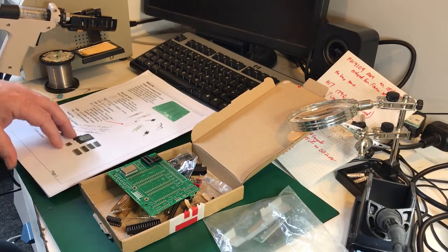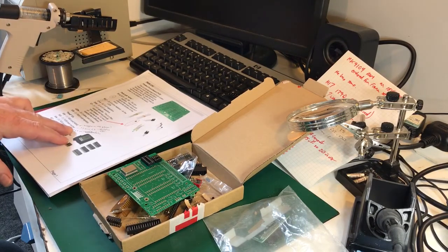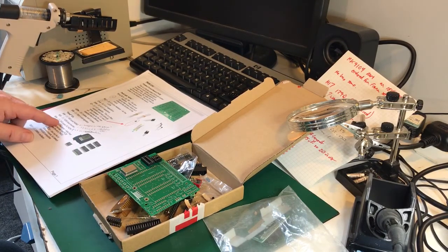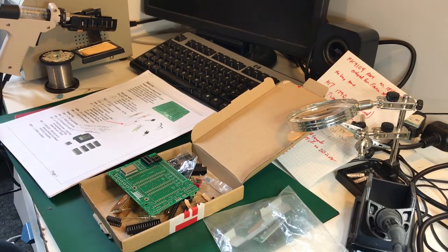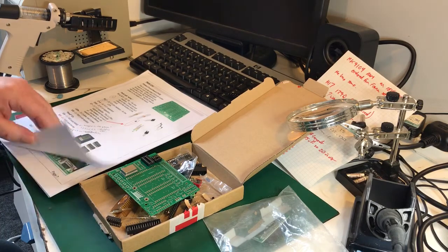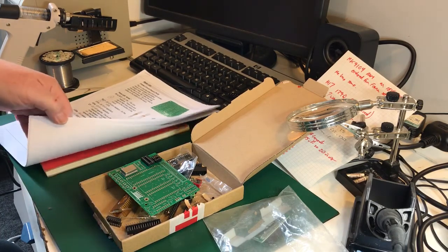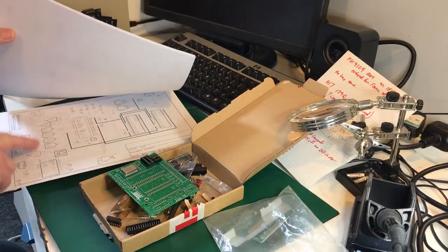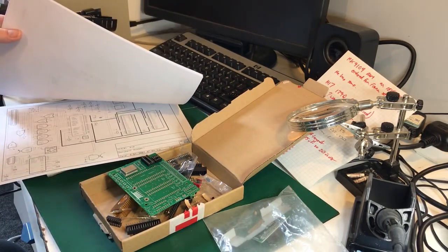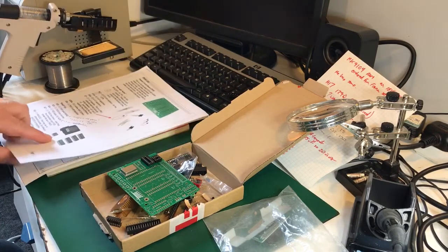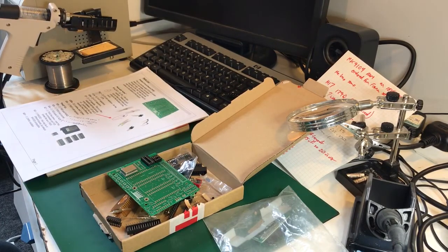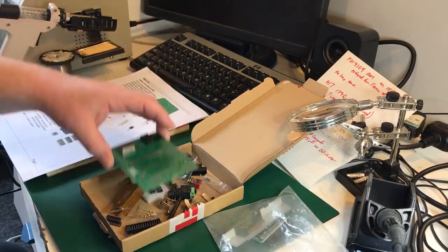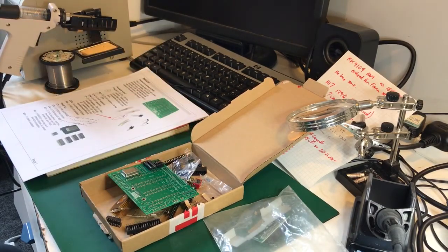So onwards, and I think I've got everything I need. The only query I've got is that one of the chips shown is the 393. I've got an LS, not a plain one. But the schematic seems a little bit mixed up with LS chips in some of them. But I've got a 7400 for the motor and the drive ones, assuming it's something to do with their drive currents. Anyway, we shall see how it goes together and give it a test in the H8.